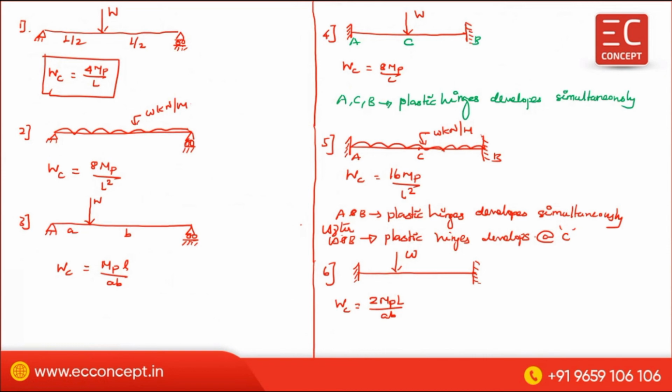Here this is point A, point B, point C. The first hinge develops at point A. The second hinge develops under the load point, always under the load point.